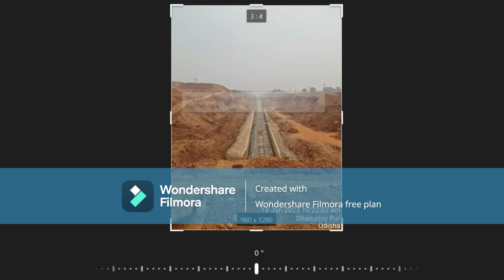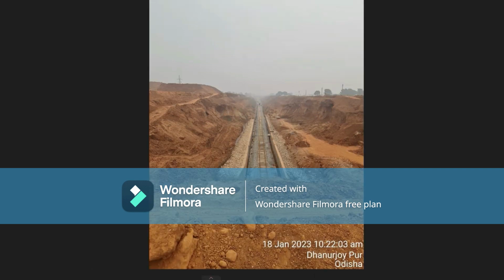Here we can see that between the sheet pile and this wall they packed boulders up to 600 mm for drainage of water. The water is poured, and fine soil is also poured here. Then they constructed here, and the wall was prepared to stabilize the slope.